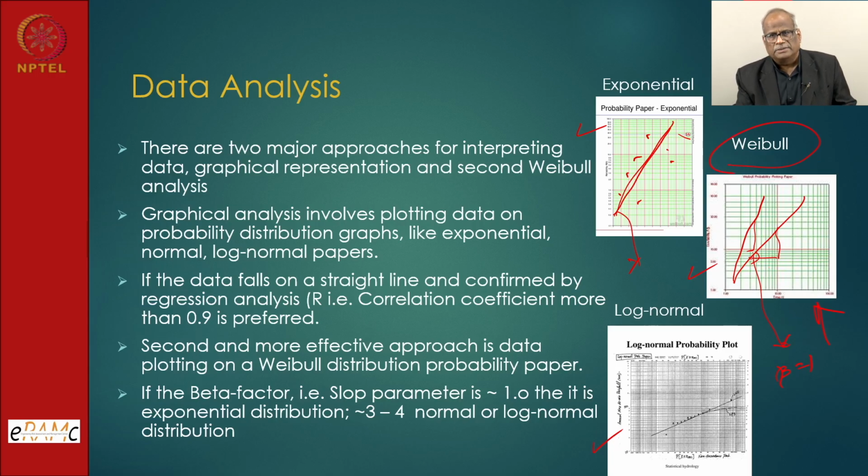In reliability there are special laboratories which put the component under stressful conditions. Those stresses could be temperature, humidity, or corrosive conditions, and the component performance is monitored from outside of the chamber. And it's not only one component, a couple of components are placed in service, and their failure or their degradation will tell us the reliability of those components.